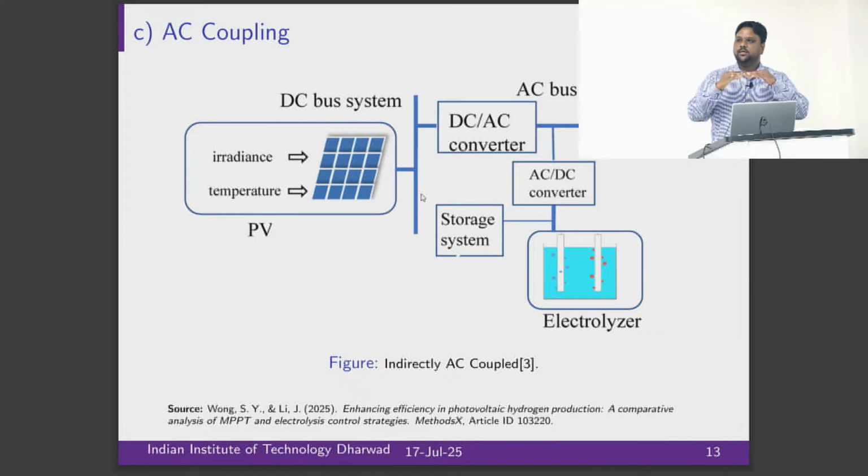But if you already maintain your MPPT, you don't have any capacity to give that active power, right? That's why nowadays the utility operator is asking you to design the solar PV inverter so that you always have a capacity of 15%, 20% extra to your rating, and you also make sure you have the capability to run at a minimum power relative to your MPPT.